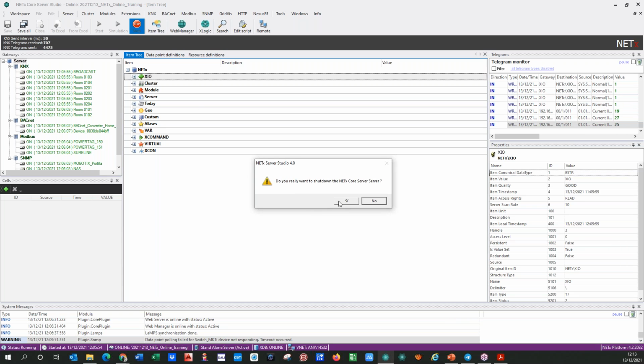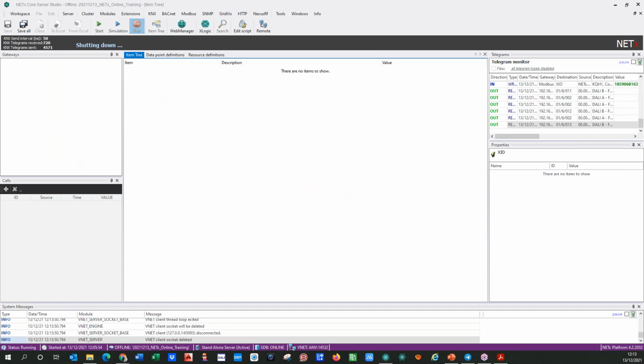But it is interesting to see. So to integrate OPC, we do as for BACnet, we stop the BMS because we are going to discover. It happens the same as for BACnet, but in this case we cannot avoid it. The BMS is not only an OPC client, it's also always an OPC server, always. So if I do a discovery, I will discover myself as an OPC server. I will show you this as an example, and then I will show you another, real OPC server.